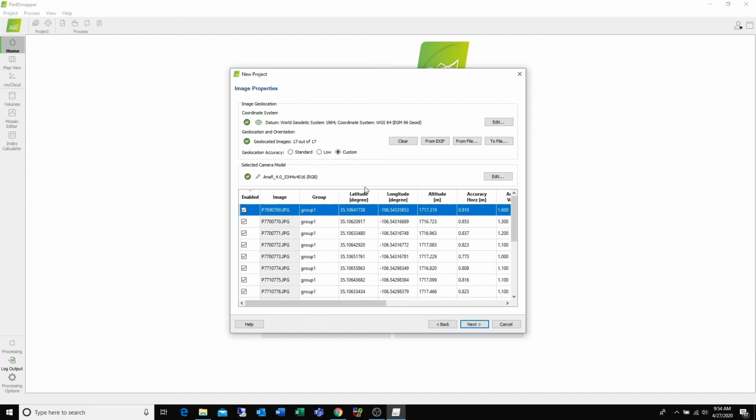You would need to add ground control points and a number of other additional quality control elements to your flight, and as part of your flight planning, if you intended to use a drone like this for production quality. Otherwise, the geolocation here is relative unto itself, aka your positional accuracy.